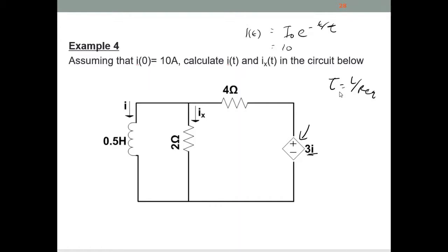It can be solved using Thevenin or Norton, but I think it's better to use Thevenin, by replacing this one as a terminal, and this becomes I0, because we know that from the inductor there is a current, but replace this one as a voltage. This is the basic concept of Thevenin: replace the terminal with one voltage, and there is a current exiting the terminal.